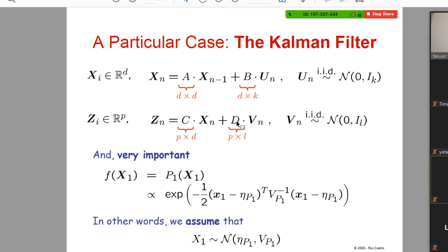When you measure, you still have noise. So in that case, you need to balance between the measurement noise and the system model noise, and then you find the optimal weight. For example, if the model is 100% accurate, you don't need the measurement, so you directly use the model to predict the next output. But that's not always the case. Your model always has error. So in that case, you might give, for example, 90%: we believe the model, and the other 10% we believe the measurement.